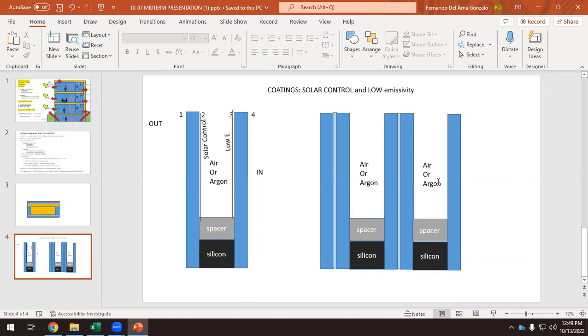First, double or triple glazing. Then, if we need safety, laminated or non-laminated glass. In high-rise buildings, in outdoor windows, we need laminated glass for sure. And then the third decision is, do we need coatings or we don't? In cold countries, low emissivity coating. In warm countries with a lot of sun, solar control coatings. So this can be that straightforward, okay?